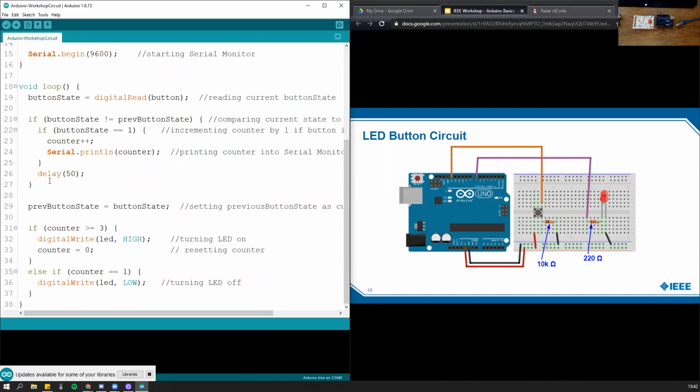We have this millisecond delay right here because this button is a physical piece of hardware. Physical pieces of hardware aren't very clean. When you zoom all the way in on the time data, when you press it, it doesn't just go from off to on. It's going to bounce a little bit, from off to on to off to on, right?